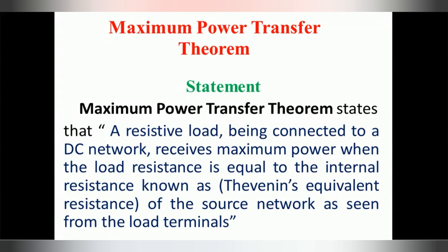In this video, let us see about the maximum power transfer theorem. The statement of this theorem is: a resistive load being connected to a DC network receives maximum power when the load resistance is equal to the internal resistance, known as the Thevenin's equivalent resistance of the source network as seen from the load terminal. That is, if the circuit has a number of resistances, we take one particular resistance as the load resistance.